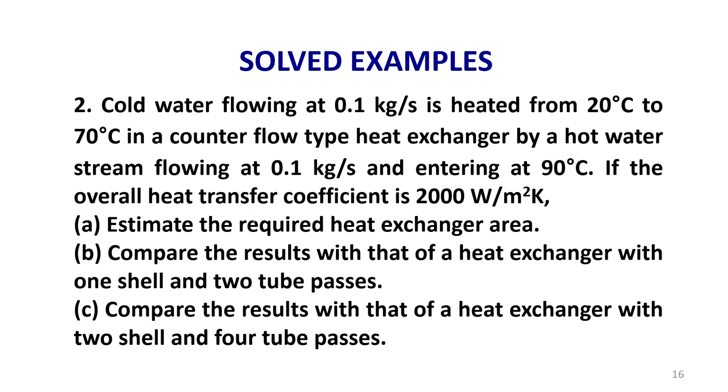Next one: cold water flowing at 0.1 kg per second is heated from 20 degree to 70 degree. If there are two temperatures given, with the inlet temperature less and the outlet temperature more, that is a cold fluid which is being heated. The source of heat for the cold fluid is the hot fluid. So, when there is heat transfer, the cold fluid gains heat from the hot fluid, the hot fluid's temperature will drop, and the cold fluid temperature will increase.